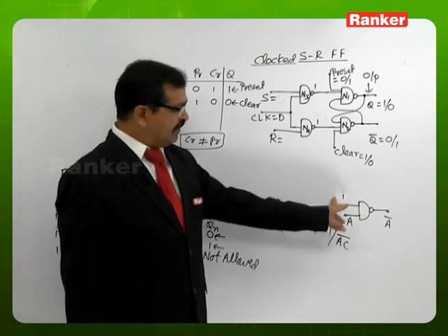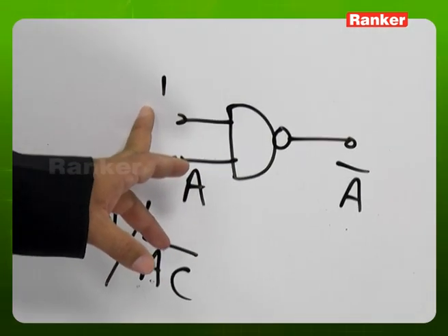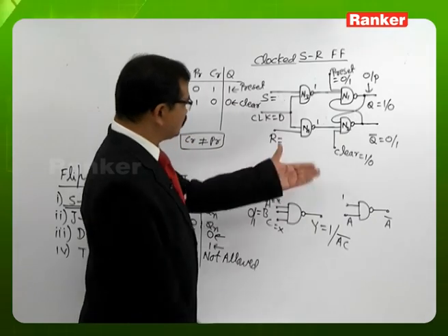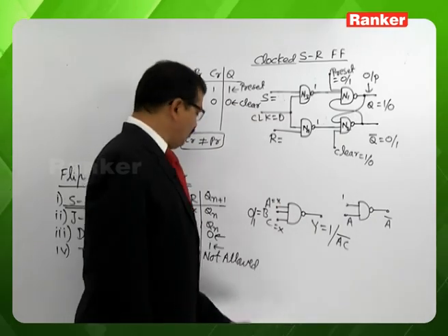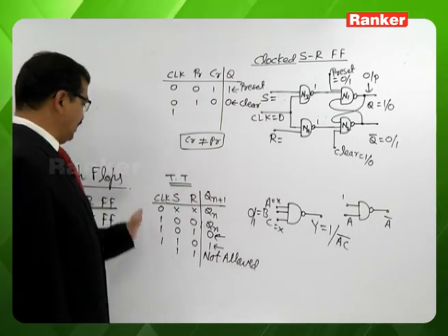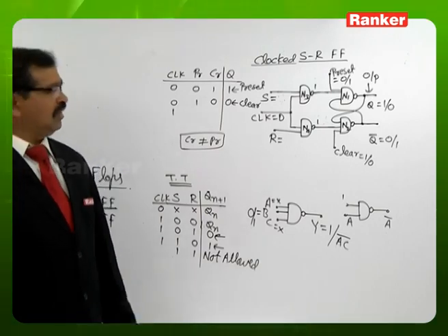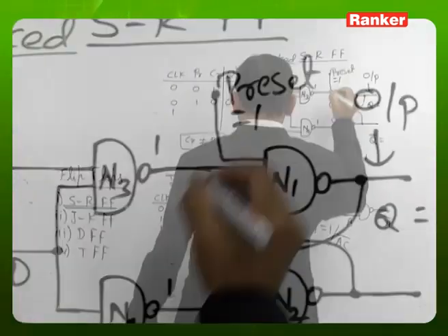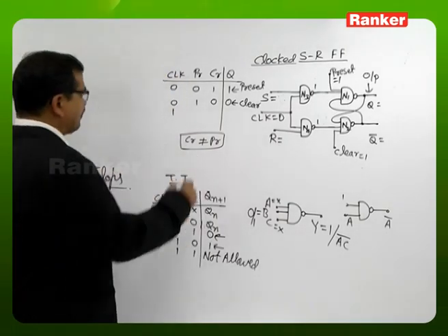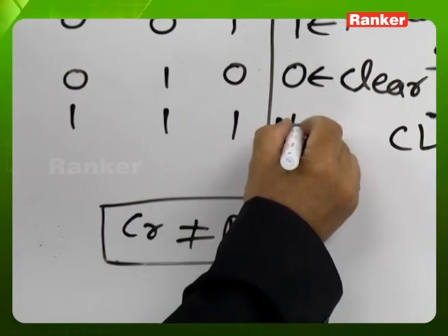If you want to make any one of the inputs of a NAND gate ineffective, that NAND gate input must be connected to 1. Based on this knowledge, to look at the normal operation of the flip-flop using S, R and clock, we are required to use the preset and clear both as 1. So it is the required condition for normal operation of the circuit.